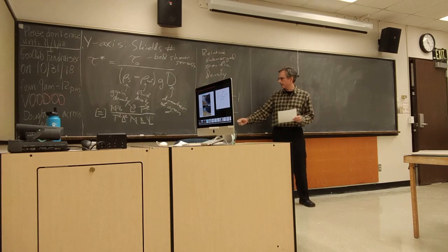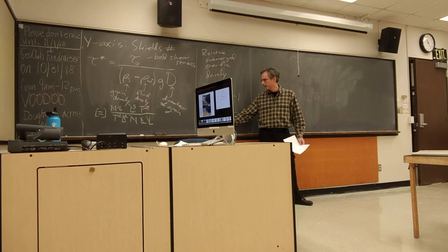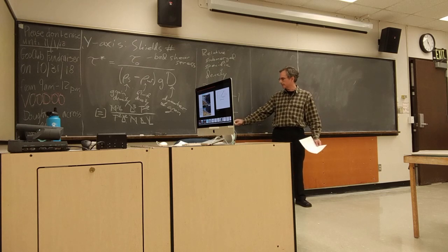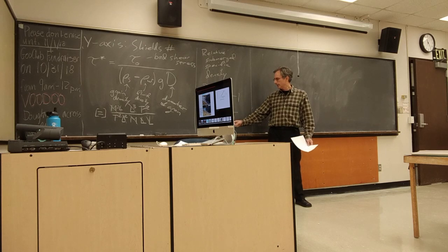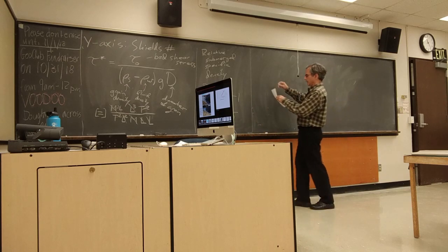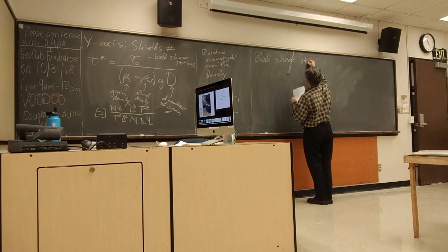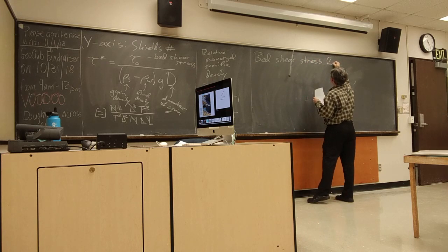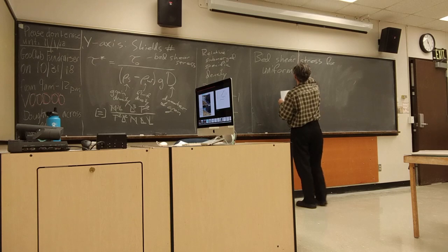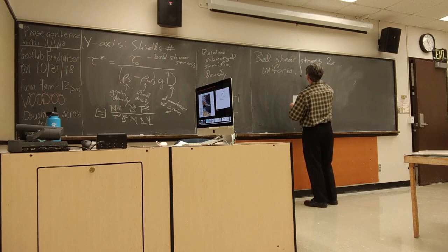So notice what we've got here. We've got a characterization of the flow, at least according to the shear stress that it's generating. We've got the fluid in density of the water, and we've got grain characteristics in the diameter and the relative submerged specific density. And we've got planetary characteristics in gravity. So let's talk about then how do we get a bed shear stress. We're going to make an approximation or assumption.